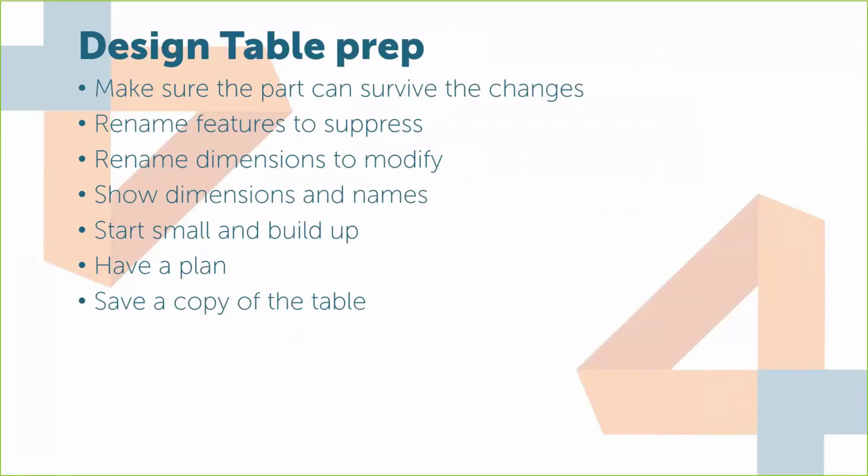So thinking a little bit about prepping a part or just any model for design tables. This is really true. I'm kind of reiterating some bullet points here. But you need to make sure the part can survive the changes. If it rebuilds in SOLIDWORKS correctly, you're good to go for a design table. If you get rebuild errors in SOLIDWORKS, which is making a dimensional change, you probably should fix that before you start to think about design tables.